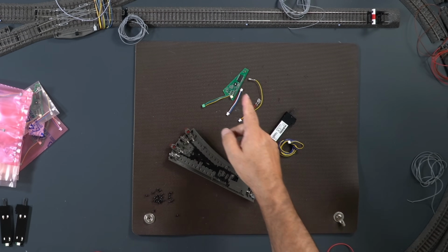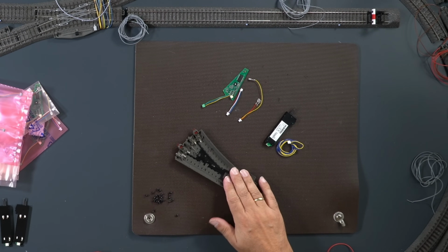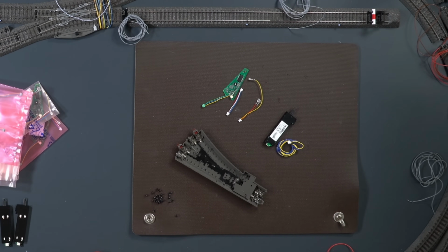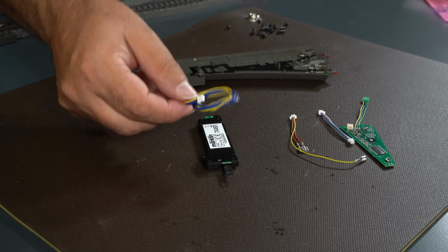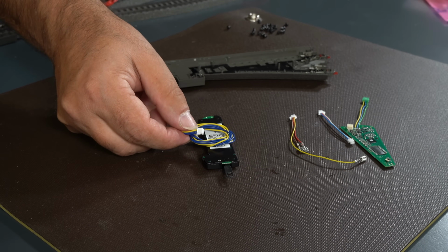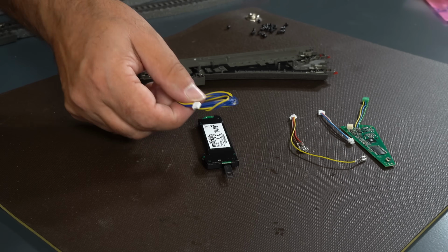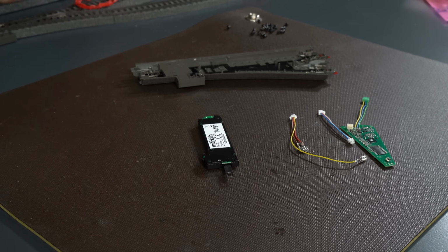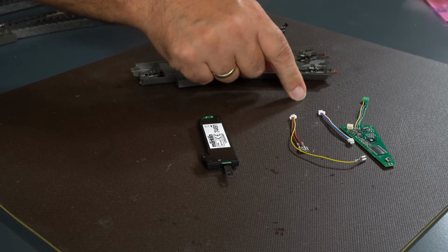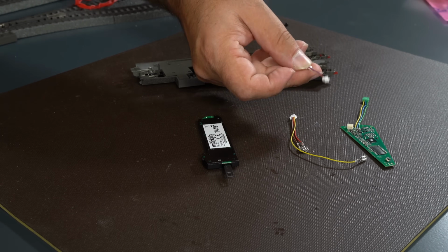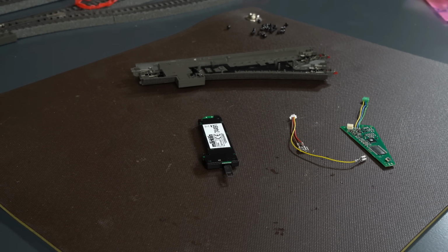So this is the turnout drive for the Märklin SEG track, and this is also the installation for the simple turnout. We will now equip this simple turnout with the drive and the decoder. As a representative for all other turnouts on the layout, the package of a turnout drive also includes this particular cable. We only actually need this cable if we want to switch this drive with an M or alternatively with control panels here. That's why we don't need this cable. And in the package of the turnout decoder, there are two wiring harnesses, and in this case, we also don't need this blue, white, red wiring harness. So this one can also be set aside.